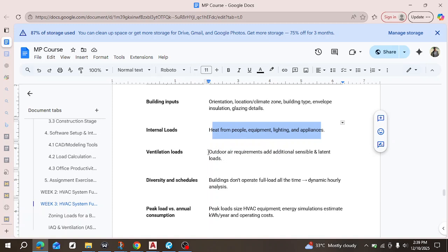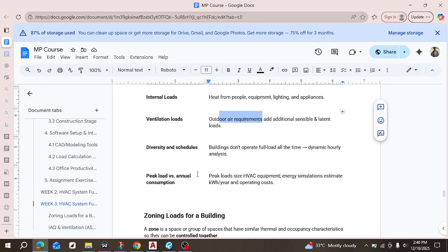Another thing that this takes into consideration is the outdoor air requirements, and these measures are more strict in commercial buildings. This is the amount of outdoor air that is supposed to be permitted into the space to dilute and improve the air quality. Because if the building keeps recycling the same air, it gets stale. So there's a need for an amount of ventilation air to enter, and also to remove some of the air in the space too.